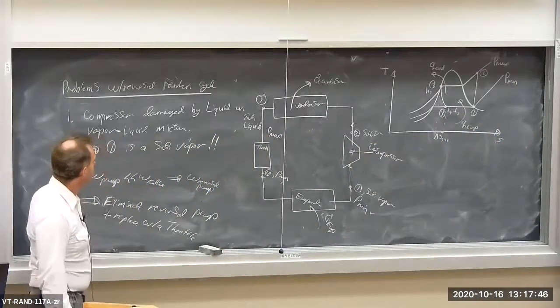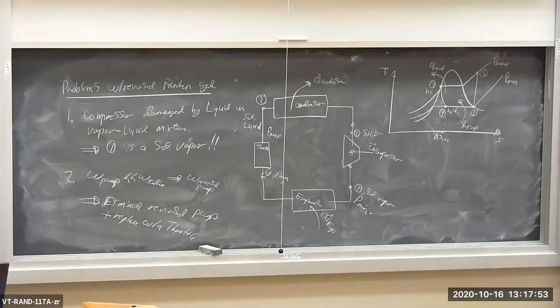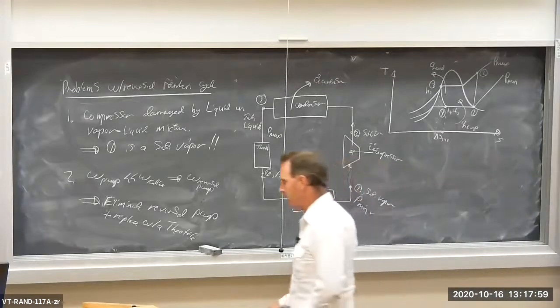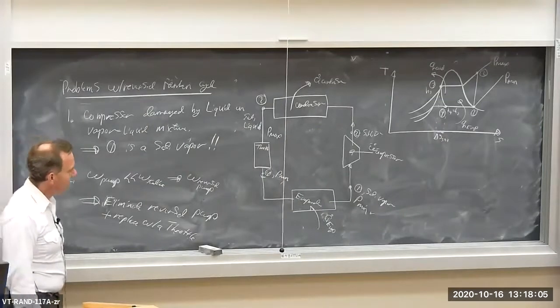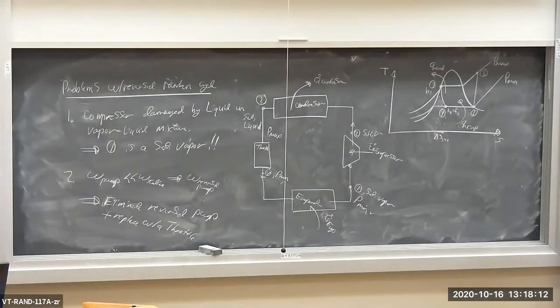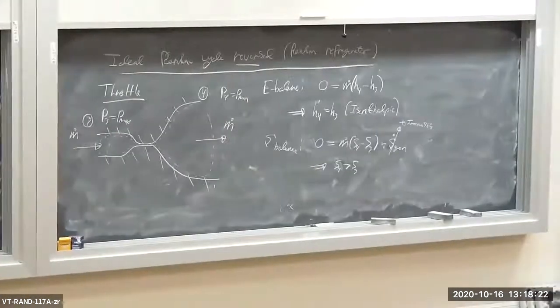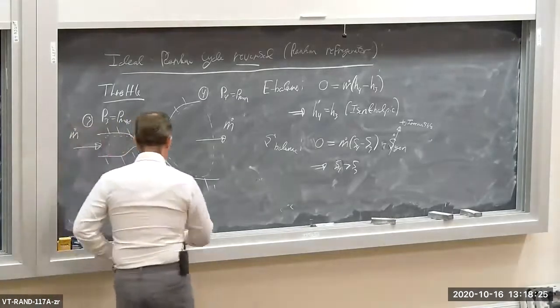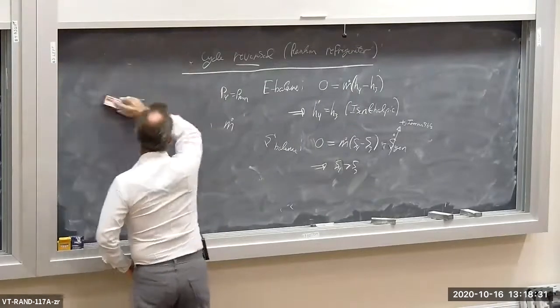All right? So this is the ideal refrigeration, compression refrigeration device. It's basically a modified Rankine cycle, where we've taken out the pump and replaced it with a throttle. And we've made the compressor inlet state a saturated vapor, okay? Now there are all sorts of deviations away from the ideal cycle. So there are all sorts of things that can happen to make this non-ideal. Let's just go over some possible variations on the refrigeration cycle from the ideal cycle.